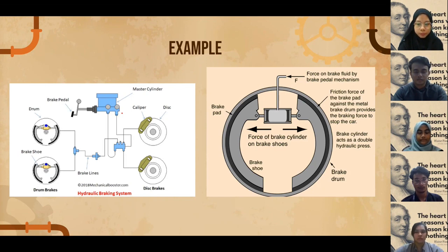The fluid will push the piston, which makes the inner brake pad squeeze against the disc rotor surface. You can see the fluid pushing the piston to the brake pad, and the piston pushing the brake pad to the rotor. As a result, the fluid's backward force will push the caliper along the slide pin, which makes the outer brake pad squeeze against the disc rotor.